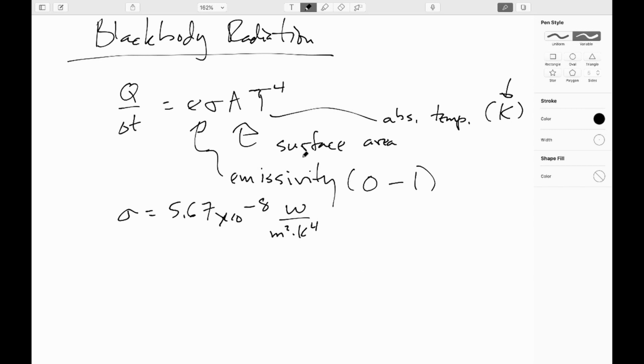number. So that's the rate at which you are either emitting heat or absorbing heat. If you're emitting, you use your temperature, and if you're absorbing, you use the temperature of the surroundings. So the net heat flow, or the net rate at which heat gets transferred, because it's a two-way street, will be the difference in the fourth powers of the temperature of the thing and the temperature of the surroundings. So this T naught is the temperature of the surroundings here.